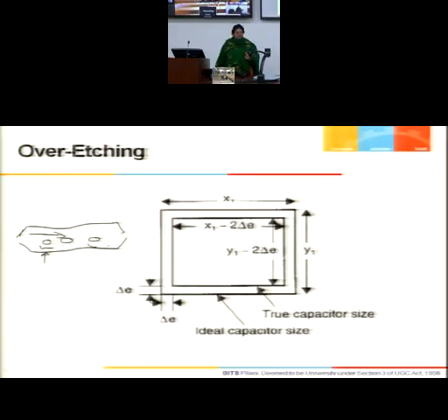This is the variations from die to die, wafer to wafer. This can also happen on the same wafer itself. This can happen where you have chips moving from one end of the diameter to the other. It seems the distance is very small, but then it does create a difference. So you have deviations from wafer to wafer. You have variations from chip to chip on the same wafer. And you have variations from point to point on the same chip. Clear? All this is because of rate of reaction difference.